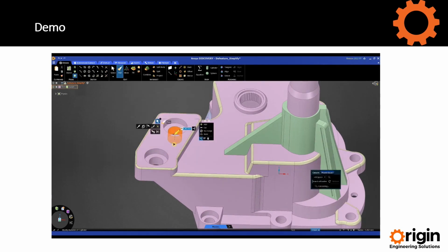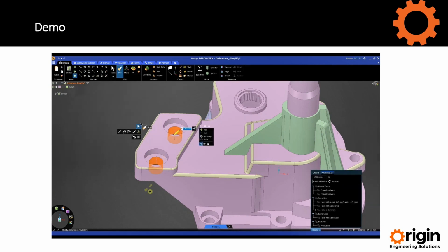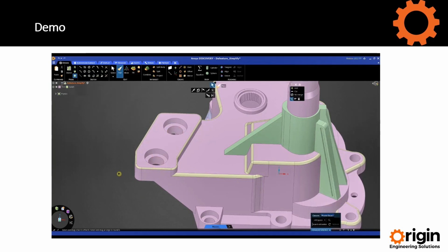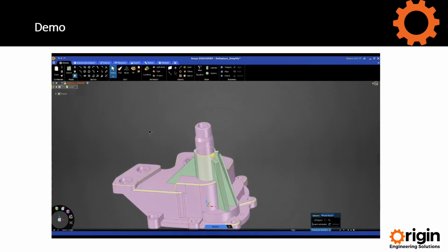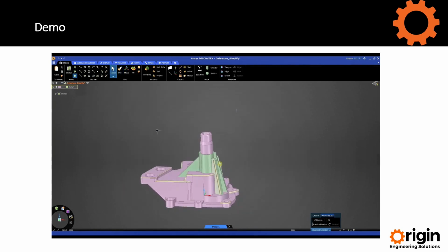Another nice thing is we can use some of our other geometry tools, such as pull. For example, if these holes weren't meant to be 5.461, they're meant to be 6 mil, or you wanted to make a quick geometry change, you can see I've just selected them both, typed in 6, and now the model's updated. So I'm just making these live changes on the model, and this is again great for rapid exploration of models when doing simulations.